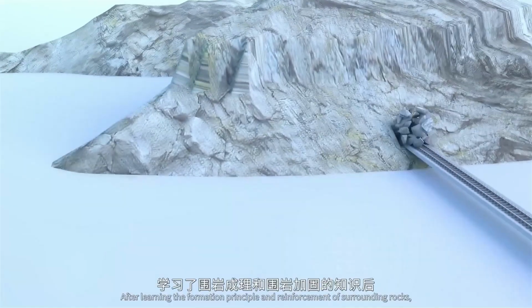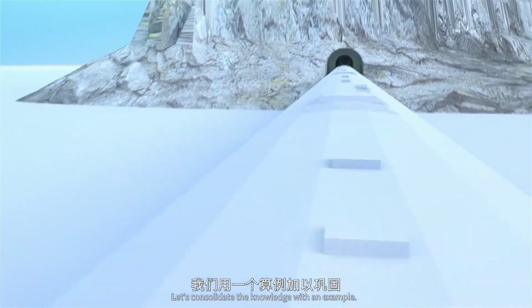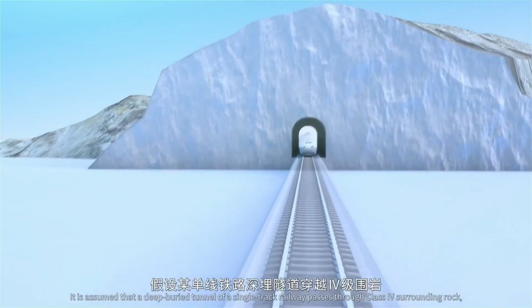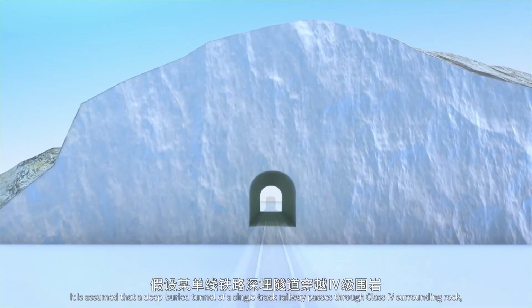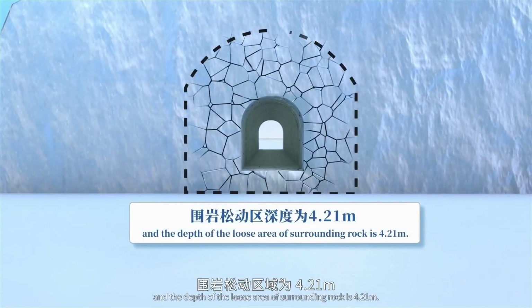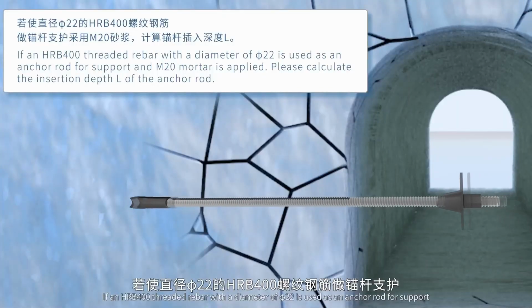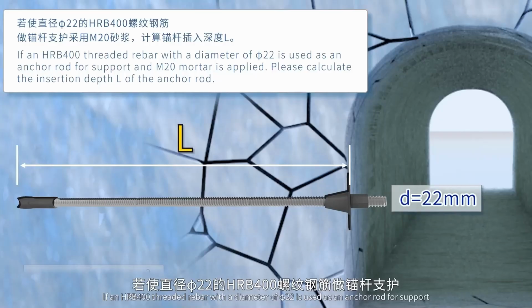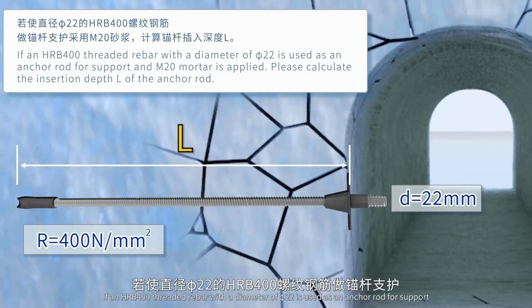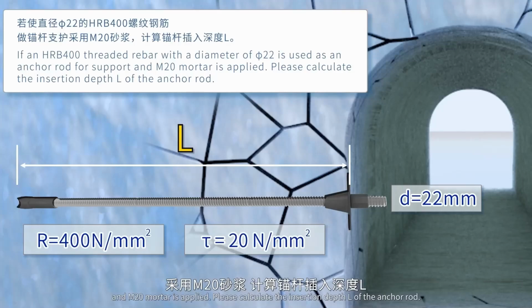After learning the formation principle and reinforcement of surrounding rocks, let's consolidate the knowledge with an example. It is assumed that a deep buried tunnel of a single-track railway passes through Class 4 surrounding rock, and the depth of the loose area of surrounding rock is 4.21 m. If an HRB 400 threaded rebar with a diameter of Phi22 is used as an anchor rod for support, an M20 mortar is applied. Please calculate the insertion depth L of the anchor rod.